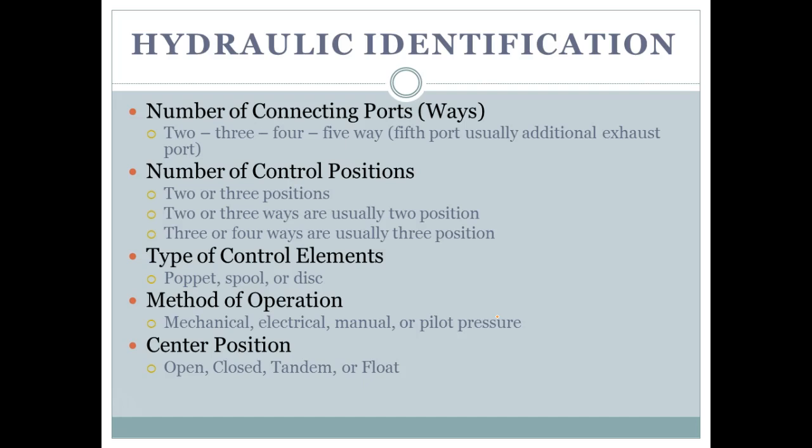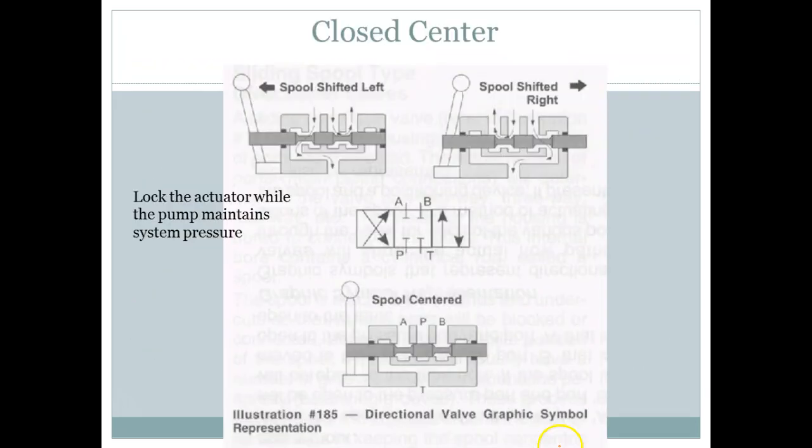hydraulics? Cheaper, the system is cleaner. Hydraulics is more efficient, but pneumatics is a cleaner system and it's a safer system. Cheaper to install, not necessarily cheaper to run, because we have to keep pressure in the system all the time. On the hydraulic system, we could actually vent the pump if we wanted to, right? Are we okay? Any questions?